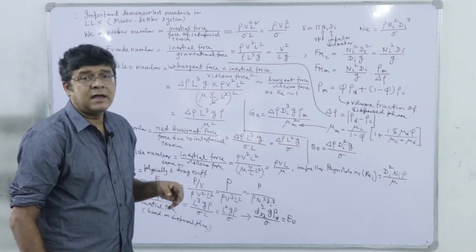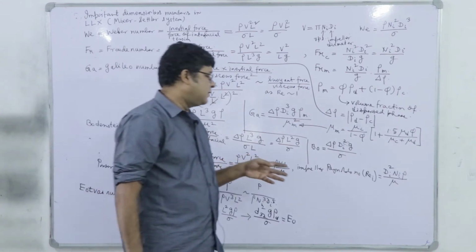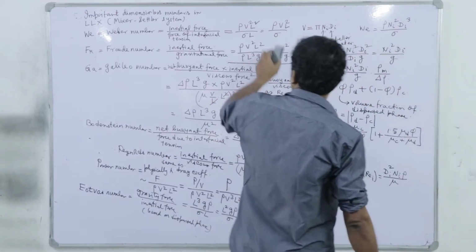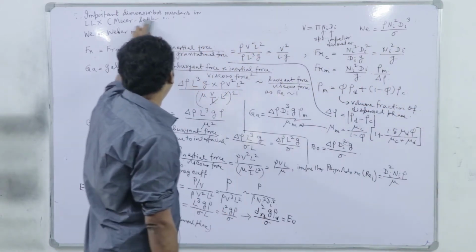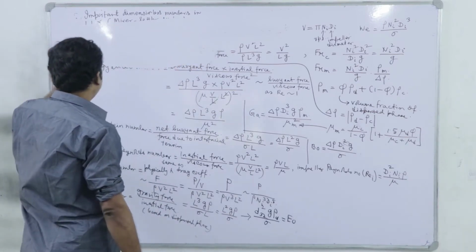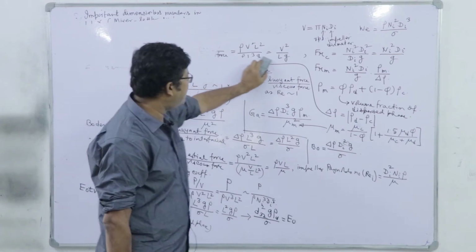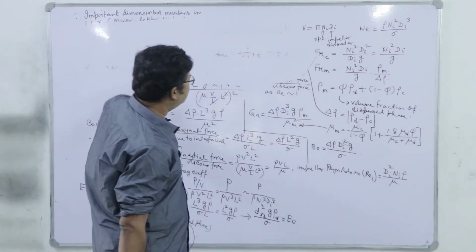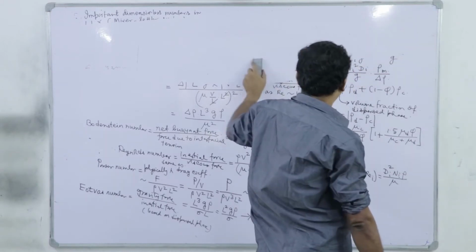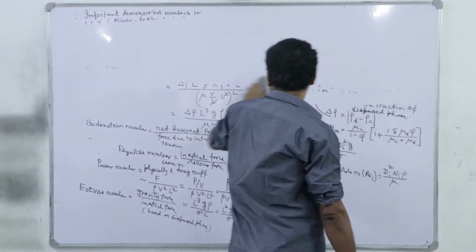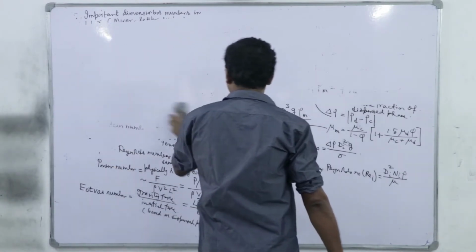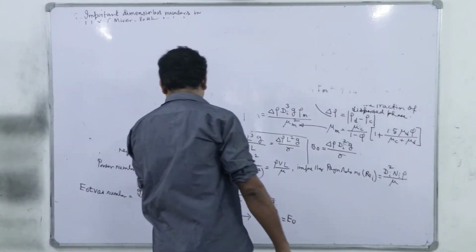Next, the power consumption. As a system, we know that it operates in the turbulent regime, which is marked by Reynolds number greater than 10 to the power 4. So, there the power number becomes independent of the Reynolds number and assumes a value of nearly 5.7 for this typical mixer tank, right. So, that was the last topic we discussed in the previous session.